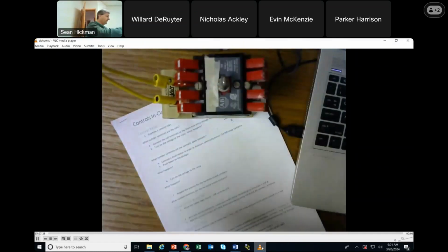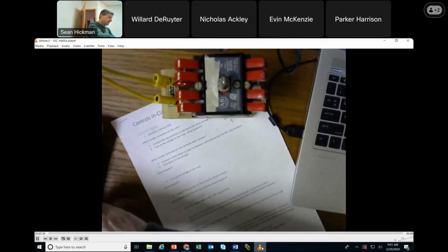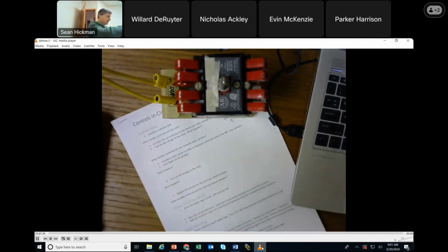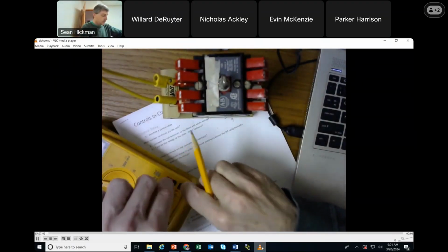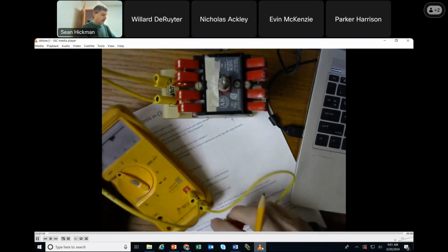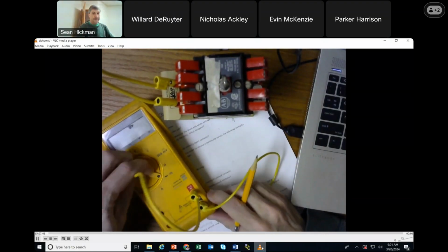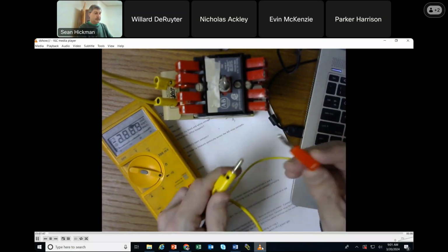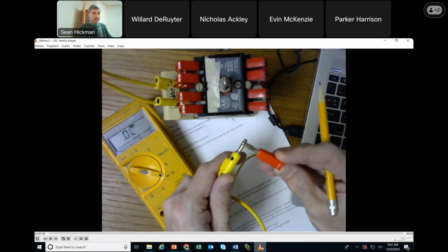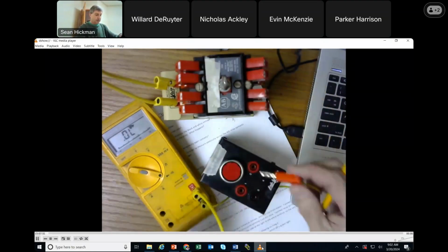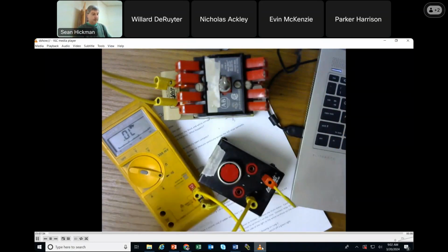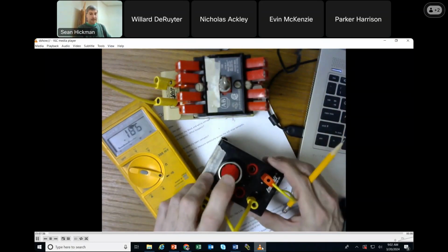Well, I've got my multimeter again, which I'll get set up. You guys can't hear it beep. All right. I'll set it up like this up here. And you guys were using a multimeter on continuity to figure out what was going on, right? Like here, I set it to the horn. That's continuity. I touch it, it's beeping when I touch. And here was the push button, remember? I put it on black, and when I push the button, it's beeping.